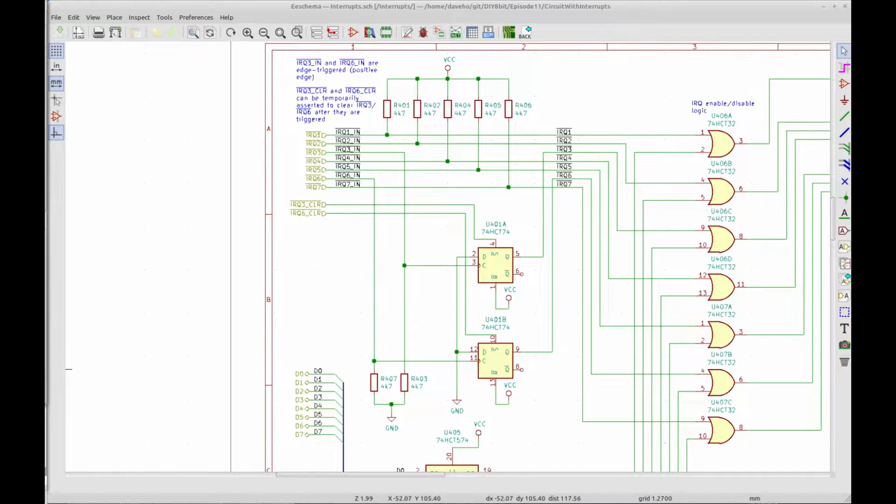be requested. Because it will not necessarily be the case that all of the interrupt request inputs will be actively driven by a hardware device, pull-up and pull-down resistors are used to ensure that the inputs are in a known, non-asserted state when not actively driven. The level-triggered IRQ inputs do not require any special processing and are forwarded directly to the IRQ Enable/Disable logic. The edge-triggered IRQ inputs cannot be sent directly to the Enable/Disable logic.